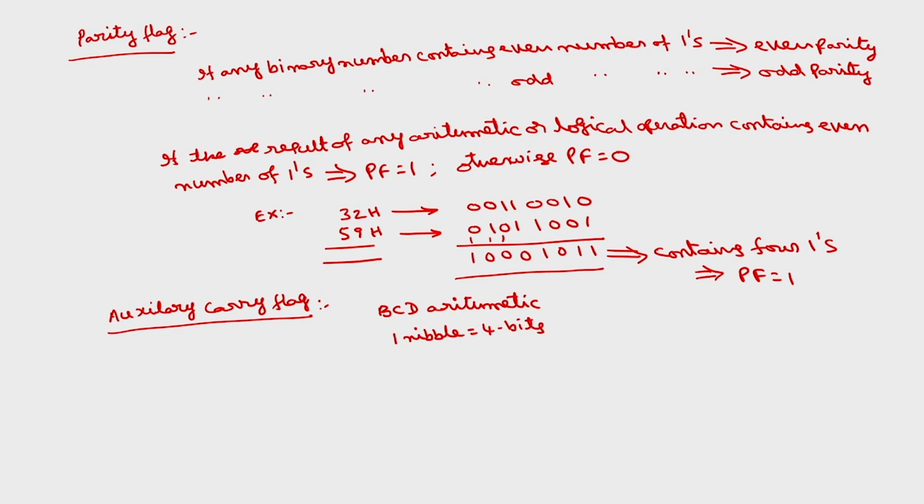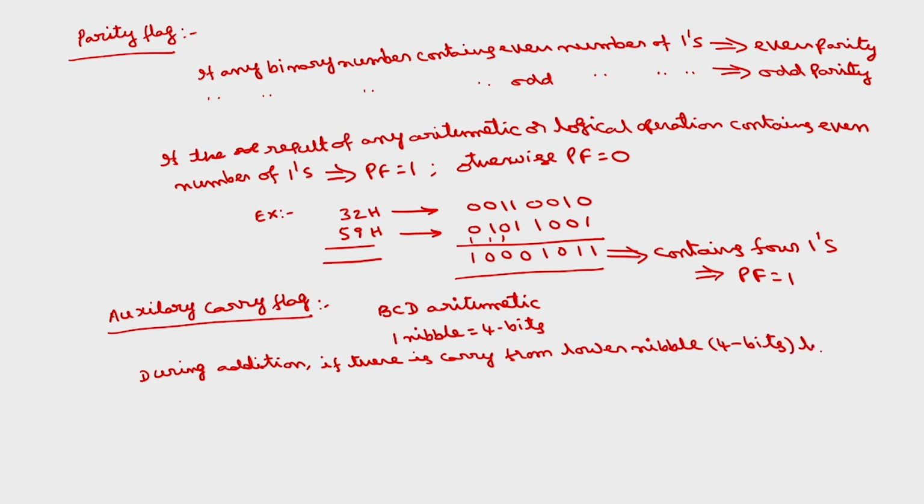During the addition, if there is a carry from the lower nibble, the lower 4 bits, to the upper nibble, the auxiliary carry flag will be set.